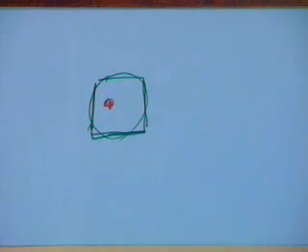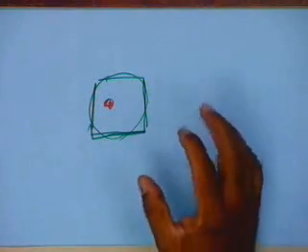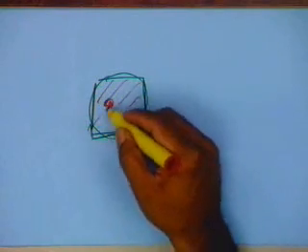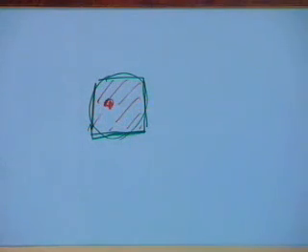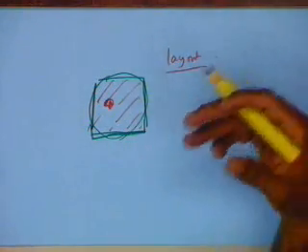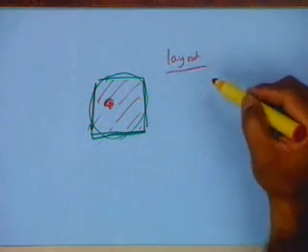So what they do is a thermal profile on the chip. It is not just that you try to reduce the overall power, you also try to distribute the power so that it gets more uniformly distributed. So you do a physical simulation after you have designed the chip in terms of the layout. Of course, this part is more related to how you are going to lay out the chip.